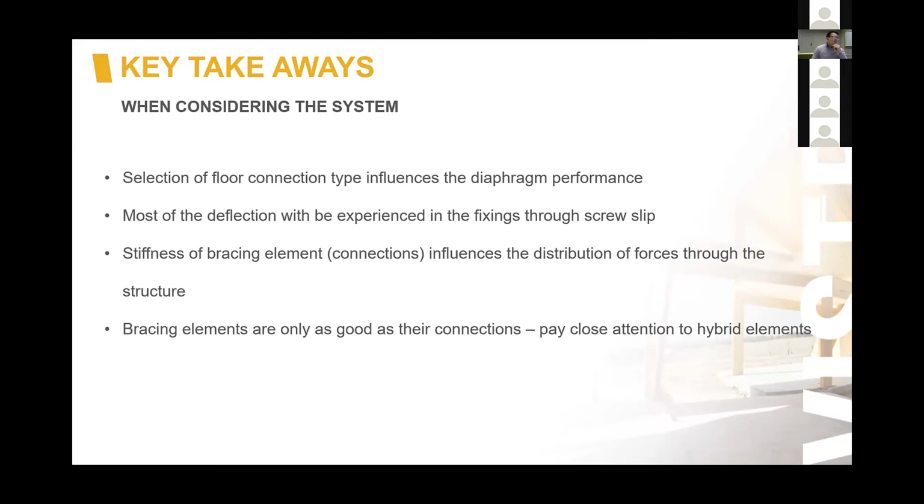And just because it's a solid wall panel, it's not necessarily going to behave like that. Bracing elements are only ever as good as their connections. I can't emphasize that enough. And really pay close attention to when you're using hybrid structures and making sure if you're using them as bracing elements and you've got concentrated loads, that the connection that you're applying reflects that.